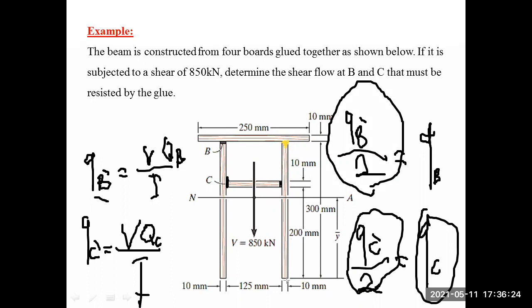An upside down L shape, okay? It's an L shape this way, L shape this way, right? It's not glued at this point. But when I need to calculate the Q, I do the same mechanism. This mechanism is fixed. I place a mirror at this location. I bring my knife, I cut it over here. I also cut over here so that I get the element disconnected from the rest of the beam.